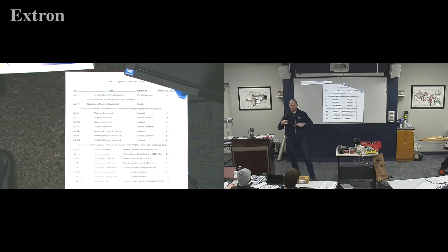The other thing is this is a keeper. It's a magnetic keeper. These are the magnets you're going to learn about that are in magnetos. As soon as you take that out of a magneto, you want to put it inside of a keeper. There's a couple of them in these kits. There should be a whole bunch of them in that 100-hour inspection. That keeps the magnet from getting weak and going bad.